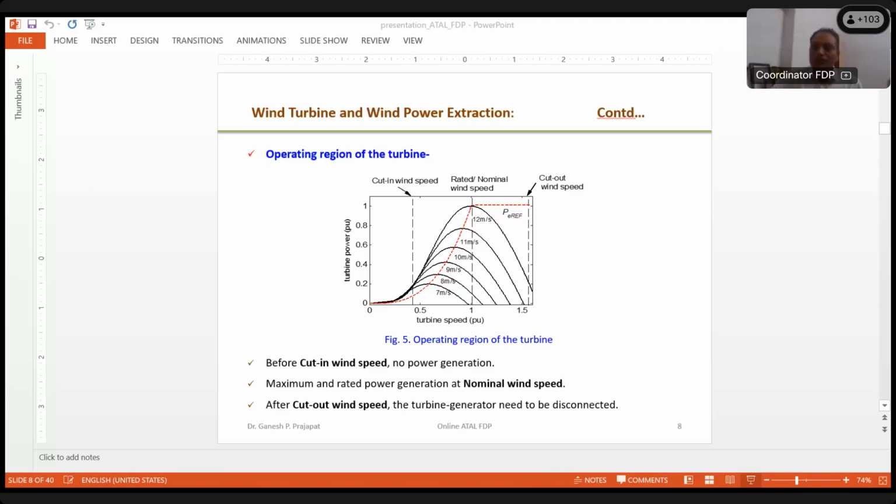Now, why do we need to generate this AC to inject it into the rotor of the shaft? Some of you might know that there are two kinds of voltages: stator voltage and rotor voltage. The frequency of the rotor voltage and current depends on the slip of that generator. The slip is the difference between the synchronous speed and the actual running speed. Accordingly, the frequency of the rotor voltage is always just a few hertz, let's say 4 to 5 hertz only.